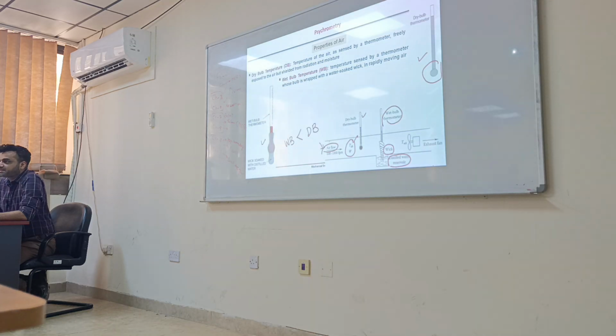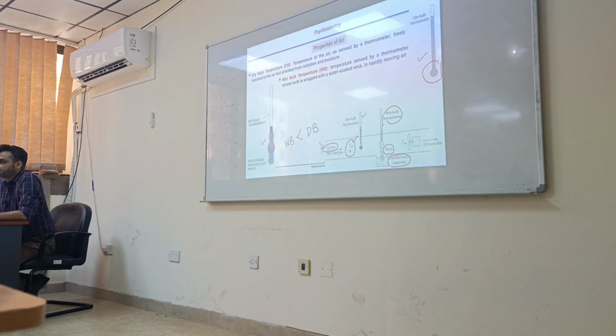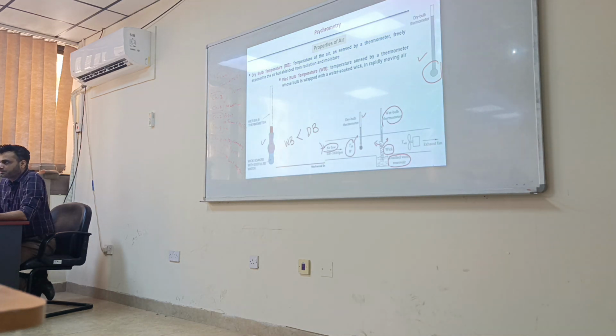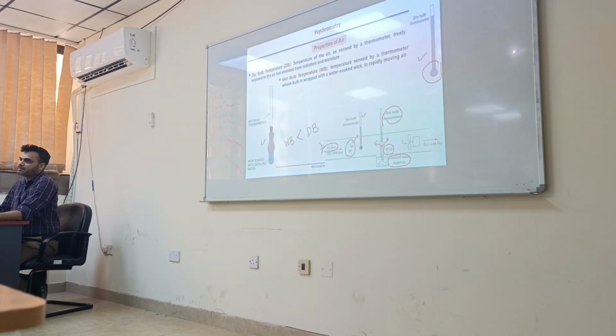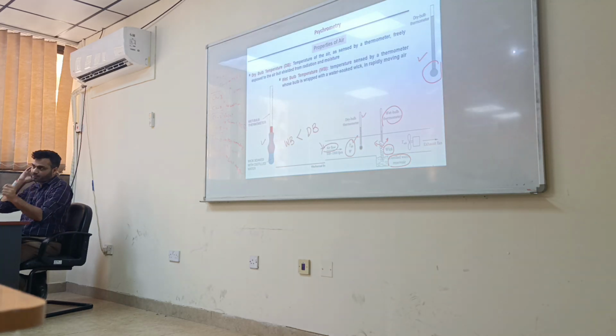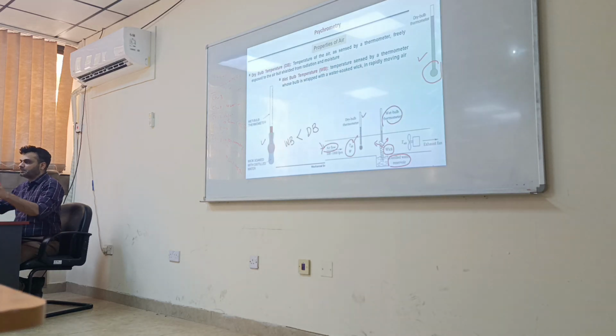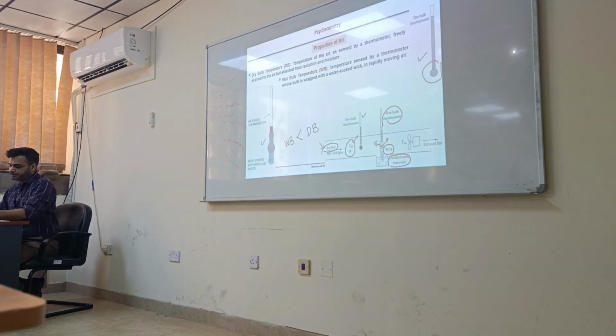If this air is very dry, then the amount of water vapor which will be added to the air will be more, because air is already very dry. It has the ability to absorb more water vapor. So the more water will evaporate, the lesser will be the temperature.